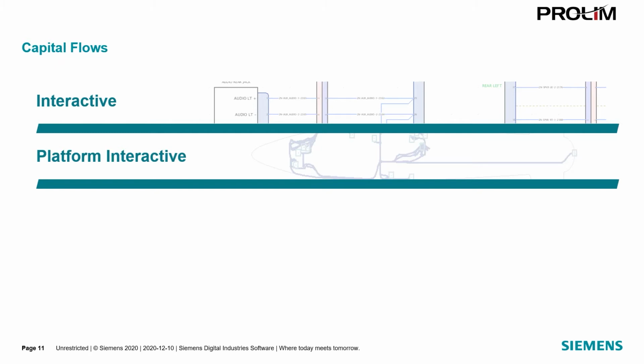You can see the pathways that your wiring is taking, and then determine from that maybe you need to route those wires in a different bundle, or across a different section of the aircraft because they no longer meet EWIS requirements, or EMI category separation and those types of things. And so that's really the difference between the interactive and platform interactive flows. You're just bringing in that topology aid to help engineers visualize and see errors and communicate more effectively with those mechanical design engineers as well.